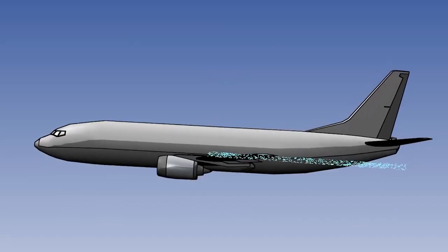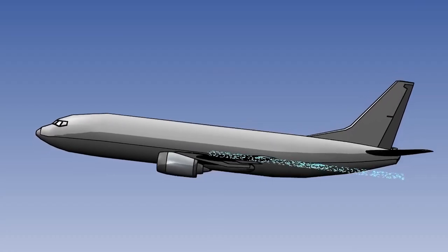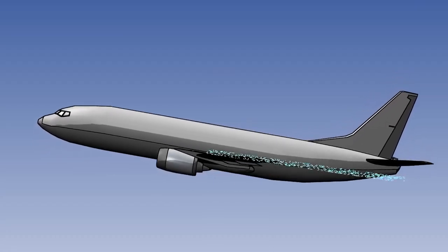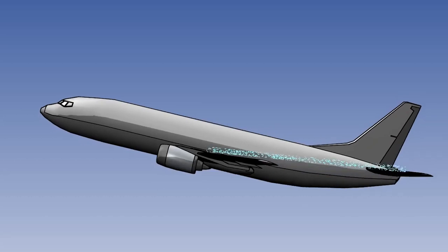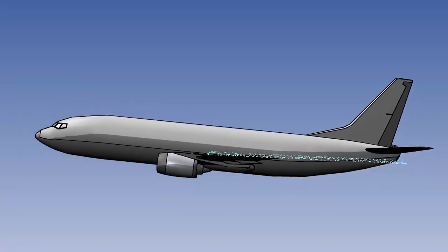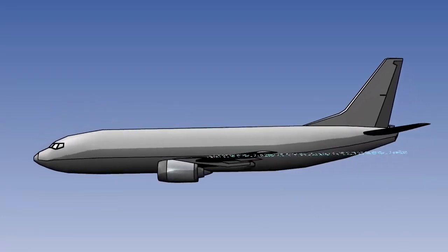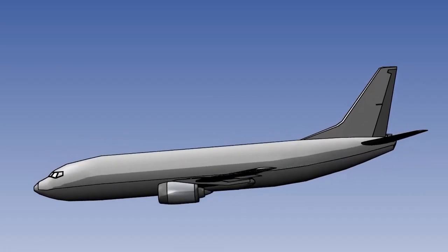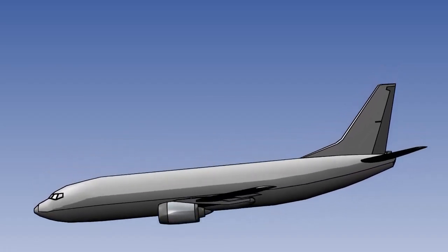If a stall occurs, either incipient or fully developed, the principal action that must be taken is to reduce the angle of attack below the critical angle to decrease the adverse pressure gradient. This action may consist simply of releasing back pressure on the control column or moving it smoothly forward until the wings are unstalled.